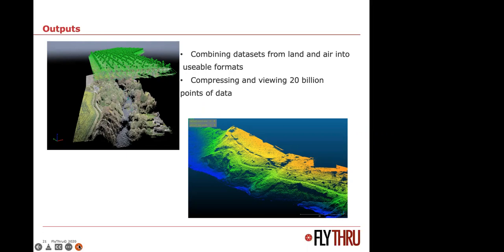But obviously a tree, a path, even a vehicle sometimes, is a static object and it's able to be seen in multiple photographs. So that was the photography, the orthomosaic. If you think about it, it's a big tablecloth that you throw over a 3-dimensional point cloud. So you colorize the cloud by taking multiple points and overlaying a tablecloth of images to give you a 3-dimensional model.